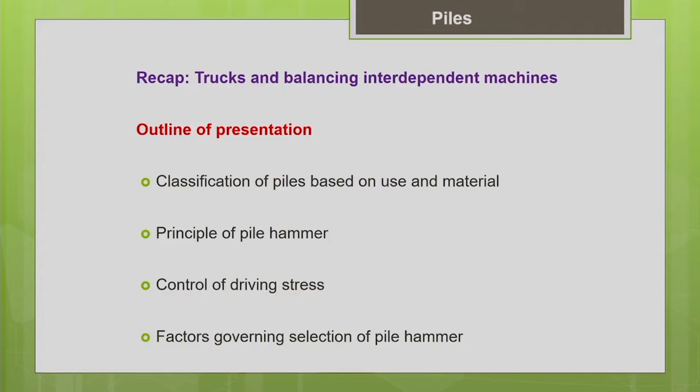Then we will move on to the principle of the pile hammer, that is, the principle of the pile driving operation. As you know, particularly the precast piles are subjected to a large amount of driving stress. When you drive the pile into the ground, say we use a pile hammer, and the driving mechanism subjects it to a huge amount of driving stress. So, what are the methods to control the driving stress?